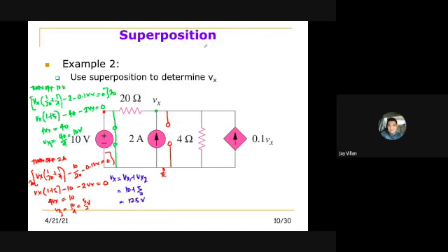So nodal analysis, Vx times 1 over 20 plus 1 over 4 minus this adjusted voltage here, that is 10 over 20, and then Vx, saan na to? Ilain, no? So minus 2 minus 0.1 Vx is equals to 0. Both currents are entering the node.